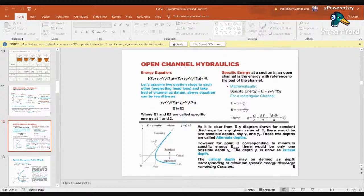Area will be written as b into y, so b will get cancelled. So your small q, that is the discharge per unit width, will be written as v into y, that is velocity into depth of the flow. Okay, so replace that into the equation, and you will get the final energy equation as y plus q square divided by 2g y square.